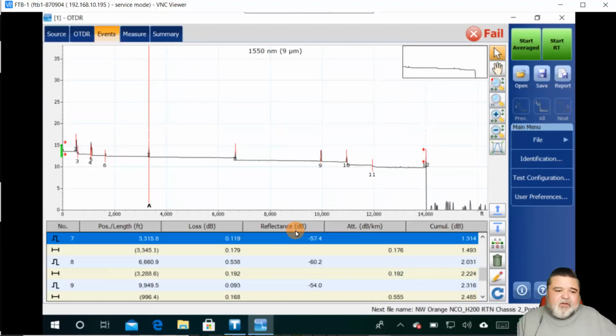Any of us who've ever done troubleshooting on the operations side, you get a call from the NOC, the Network Operations Center, saying, hey Kevin, you're taking bit errors on that one system. I take my power meter, plug it into the receive side, and I have good power. Then I start cleaning fibers. Why am I cleaning fibers? I'm cleaning fibers because of reflection, not because of power. I have good power for the system, I don't have good reflection. You can have good water pressure, but that doesn't mean the water tastes good. So those are two different things in this situation.